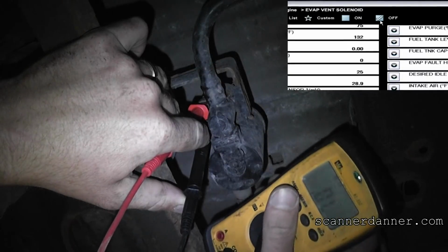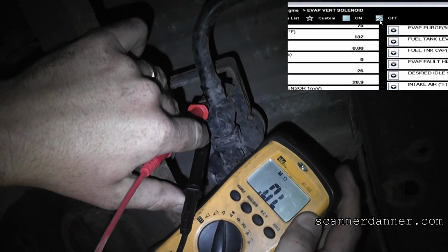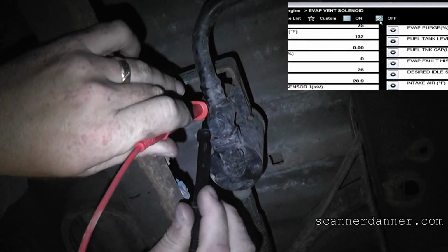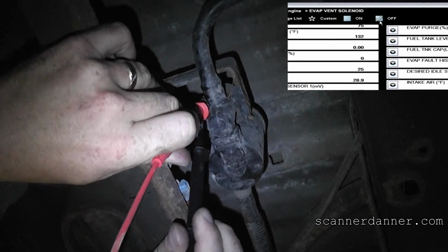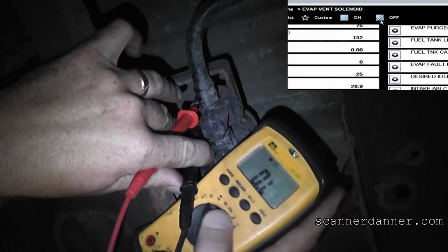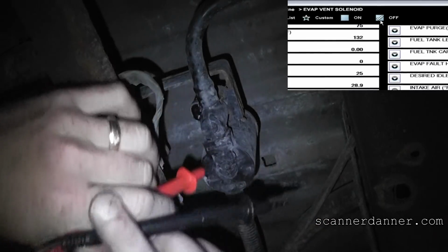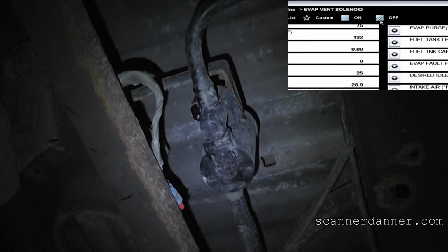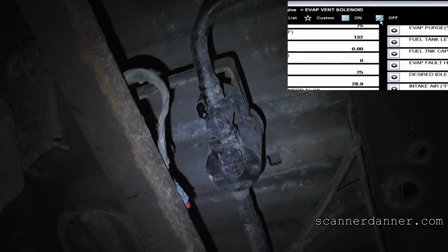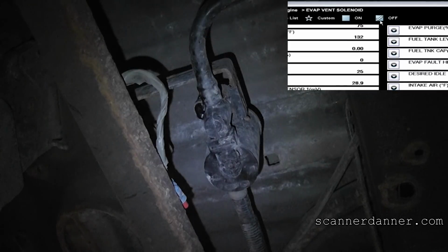That's on my mega ohm scale, and I'm reading OL, megaohms. Let's make sure I'm making contact of the pins. Definitely making contact. There you go. Open solenoid. No question about it. Even if this read some decimal point, I was not going to be concerned. Doesn't change our problem. Any questions on the resistance check?